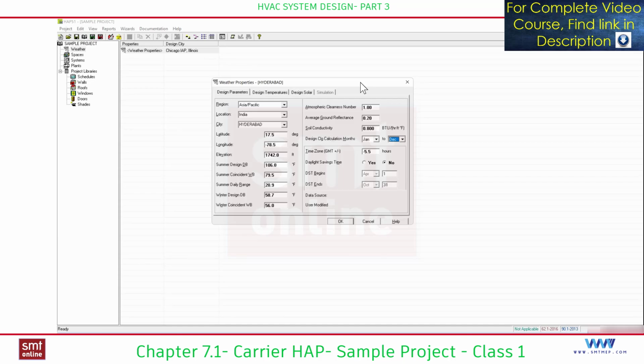But now we are dealing with high configuration, with minimum 8 GB RAM with i5 or i7 etc. So even if you select January to December for a small project, you'll not feel that difference in the calculation time. It may increase by some seconds, but it will generate the report quickly. In case of multiple spaces, like 100 spaces or multiple spaces with different systems, this option will help to save the time in the calculation.